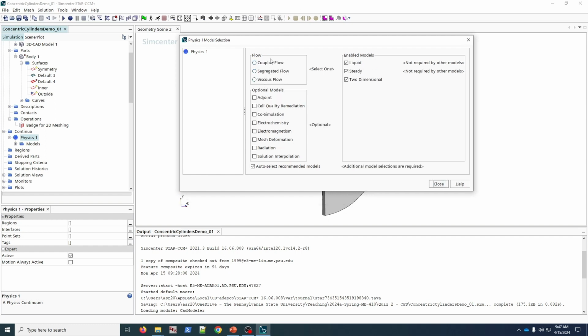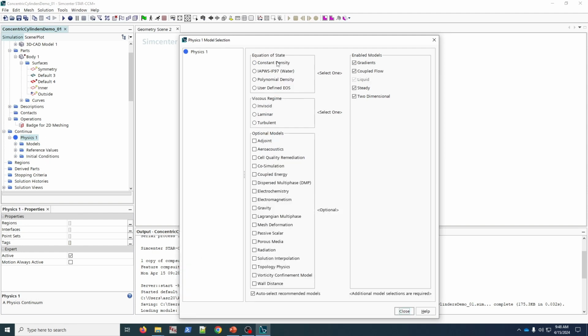We have different ways to represent the flow or solve it. The discretization that I think will work best for us is the so-called coupled flow approach, where the governing equations for momentum, continuity, and in our case energy will be solved simultaneously. And since we've got a natural convection problem where those interact in a complicated way, it'll be a bit more stable to use this approach.